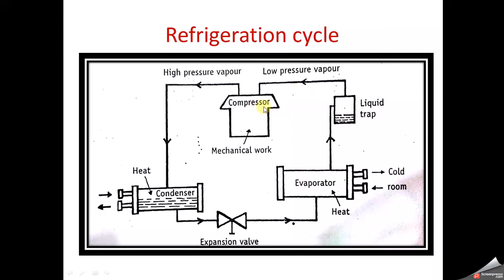During this compression process, compression is added to the vapor and the pressure will increase. Okay, so once the volume is getting filled up, that will increase the pressure, okay, as more and more vapors are entering inside the compressor. The compression is then adiabatic, okay, and on the discharge side it produces a supersaturated gas. On this exit side, a supersaturated gas will be released.